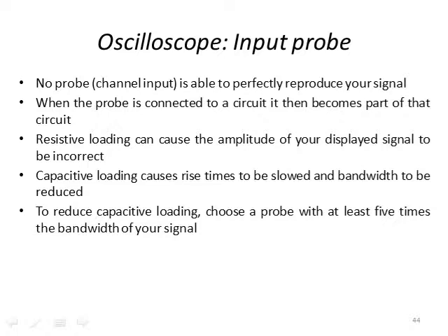Right? If you have something that's switching, moving from a low level to a high level, ideally you want a perfect step function. If you have this capacitive charging function, you don't want that to be due to your probe. You want it to be a result of your circuit. So how do you decouple that? You have to choose the resistive and capacitive loading of the probe to match the measurement that you want to do.